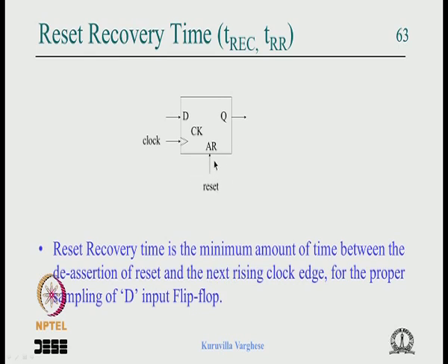So now, understanding the reset recovery, what is the solution? If you say let's synchronize the asynchronous reset, then it is like synchronous reset only, because what synchronous reset does, we do it outside.